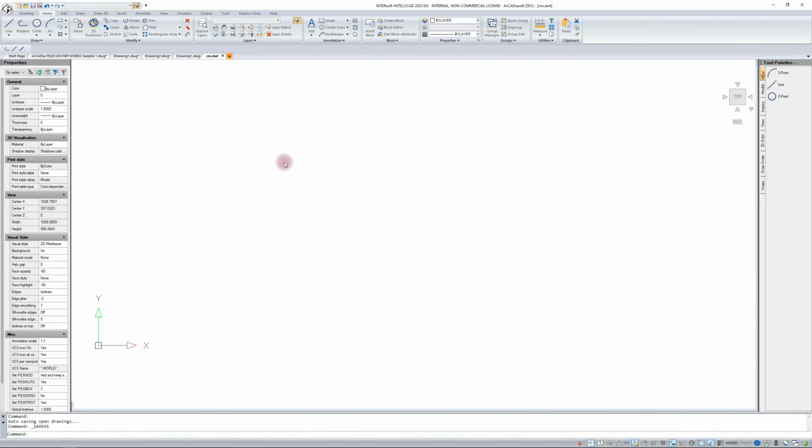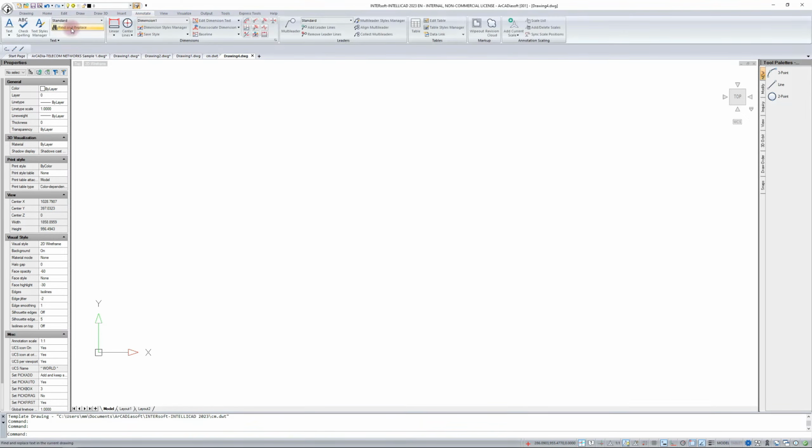And now I create a new document, a clean and blank one. It looks exactly the same as the one when I was starting to draw, but now I'm going to take it. I'm going to introduce dimensioning. Then we'll go to the description ribbon, dimensions. We have the style, we select it, we enter it, and the value is visible.